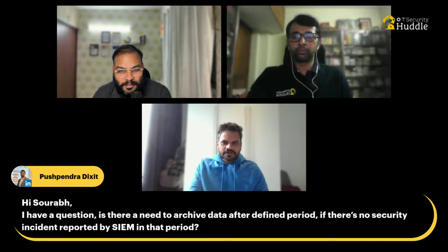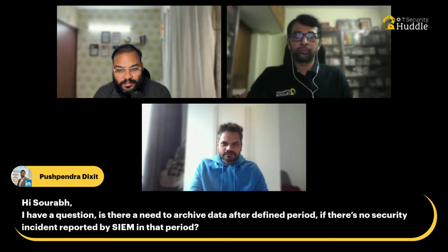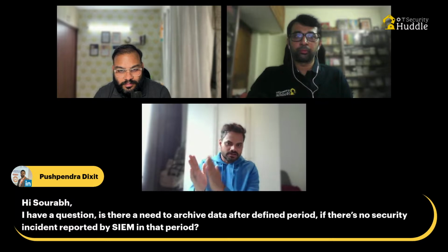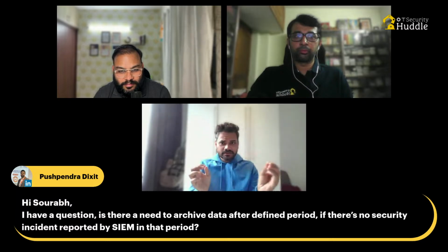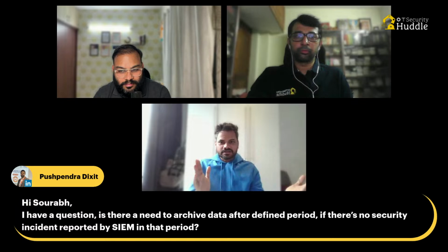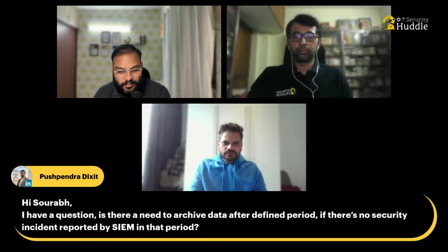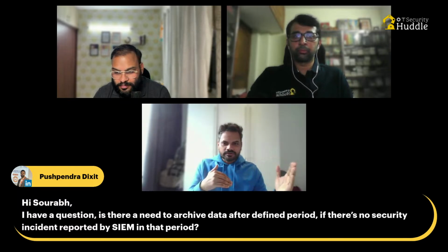A data diode is a one directional hardware device. It's really a one directional hardware device, unless you are using a flip model, which is not a one way device. So a data diode is a one way, physically separated link using LEDs, where data is transmitted from the LED. It's a physical separation so that nothing can come from the receiver to the transmitter. We use it if we want to send data from one place to another place and we do not want any back communications.